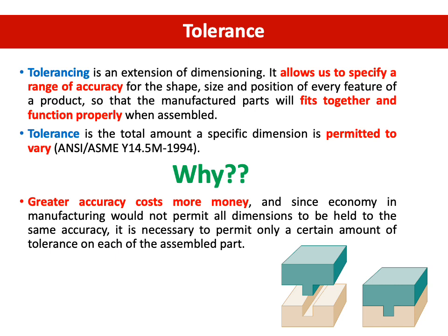Tolerance is the total amount a specific dimension is permitted to vary. Tolerancing is an extension of dimensioning. It allows us to specify a range of accuracy for the shape, size, and position of every feature of products, so that the manufactured parts will fit together and function properly when assembled.